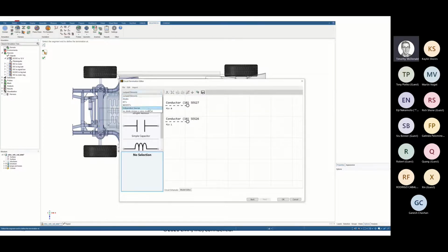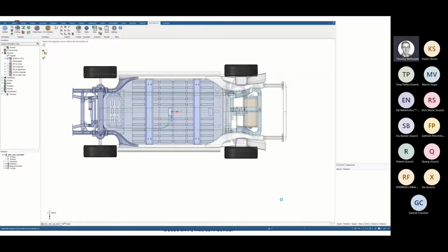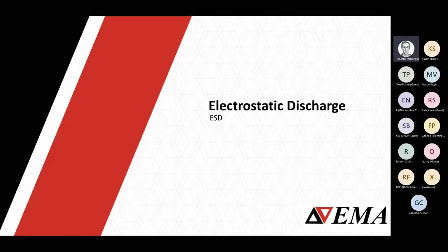So I can go on the web to the website of that component manufacturer, in this case for these TVS diodes, I can download their component file, SPICE, IBIS style component files, and I can import them in one step. And I can add that diode protection to my circuit, and I can rerun my simulation, see how the diode helped or didn't help my EMC performance. So for immunity, having the circuit can be very helpful.